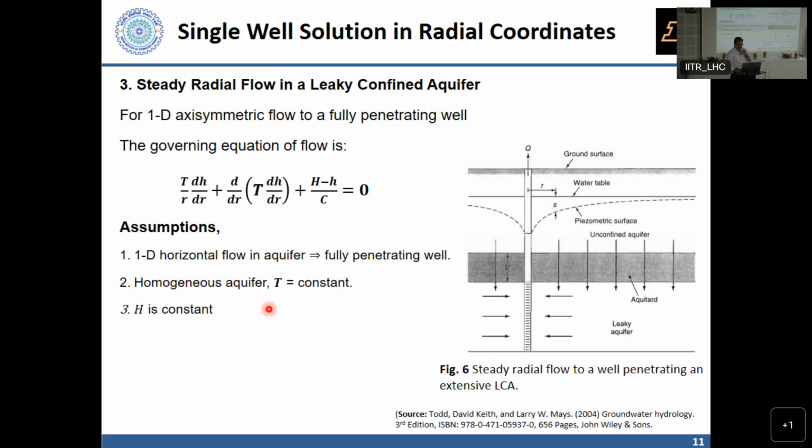One is, in the previous examples, when we did not have leakage, the flow that was coming towards the well at any distance r, through that cylinder of radius r, was not changing. But because now we have leakage, that means water is entering the aquifer, in this case vertically, so the amount of flow that's moving towards the well is going to be changing with r now. At some distance r, you have a certain amount of water coming in from that cylindrical surface, but as you come closer, all this leakage water is also being added and being pulled towards the well. So as I come closer and closer to the well, the amount of flow coming into the aquifer towards the well is increasing. And this is, of course, assuming that the leakage is in some sense positive. It's adding water to the aquifer. If, on the other hand, leakage was leaving the aquifer, as you came closer and closer to the well, you would have less water coming in towards the well.